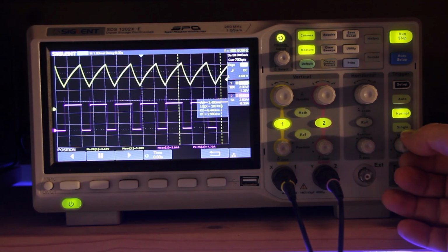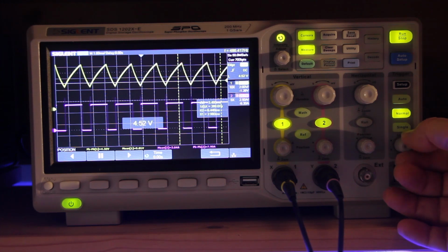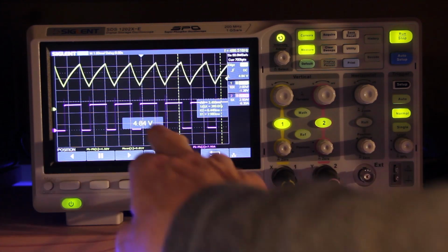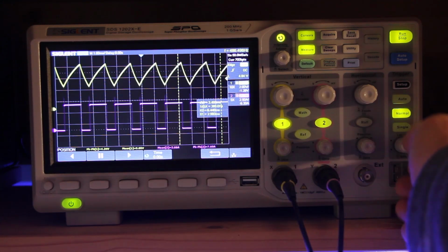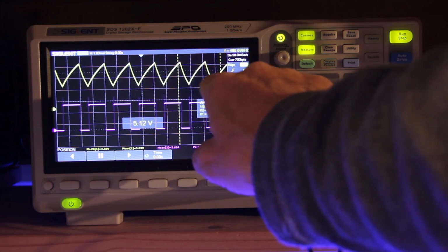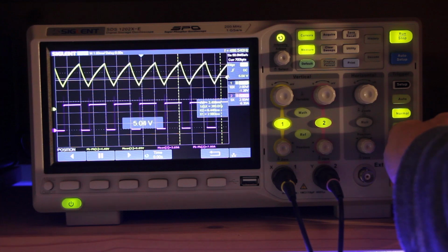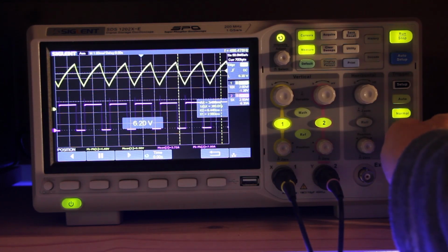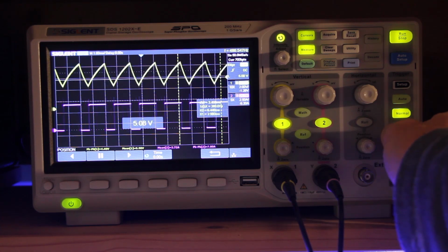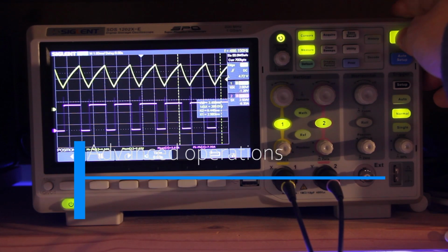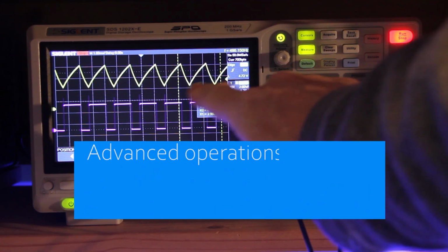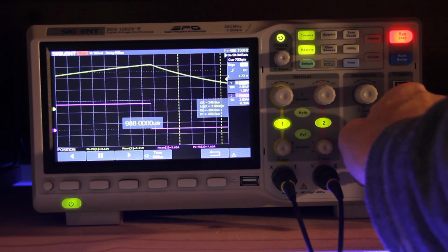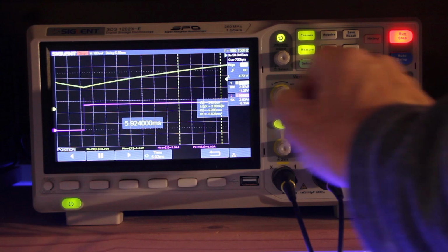An interesting feature is that moving the trigger lever, we can see not only the voltage of the lever, but here we can have a feeling of the lever that is projected on top of the waveform. Another advanced feature is that we can stop the instrument from grabbing samples, expand the view, and scroll not only after the triggered event but also before.